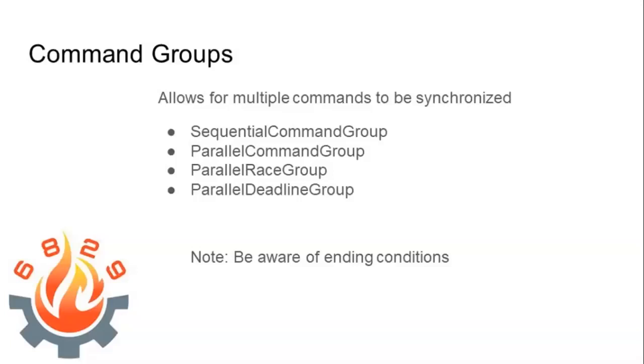If I had to lift up, drive back, and lower as separate pieces, and I put them together in a group to be one virtual command, it allows me to say, you know what? I want the driver to be able to drive as soon as I get done raising it. So I go to the command group and I just remove the back away. So now it just does lift up, waits a second and lowers. Now use the drivetrain. So you could do stuff like that, and it's easy to change it around, right?